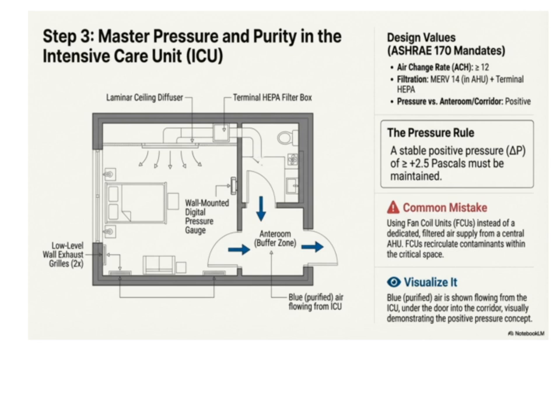Another important point is that fan coil units are not permitted in ICUs. Instead, all air must come from dedicated air handling units, or AHUs, specifically designed for this purpose. This dedicated supply helps control airflow and maintains the strict infection control standards outlined by guidelines like ASHRAE 170. Altogether, these measures are vital to creating a safe, controlled environment in ICUs, which is a key part of our